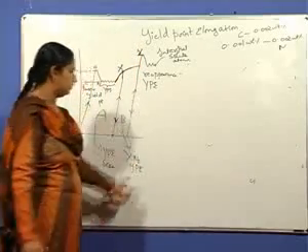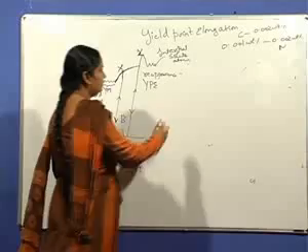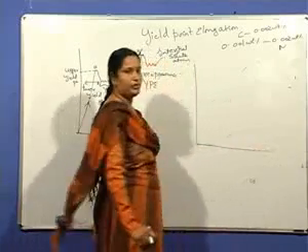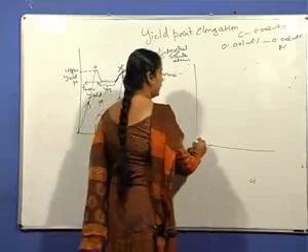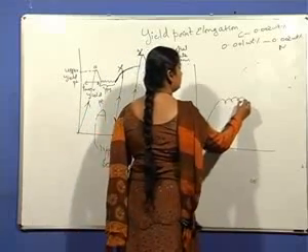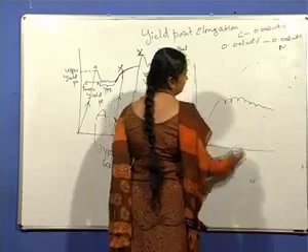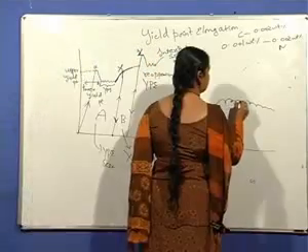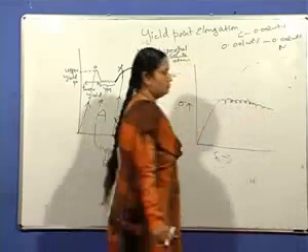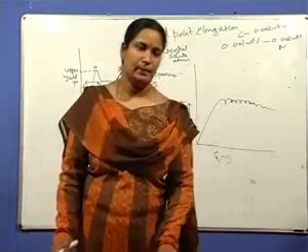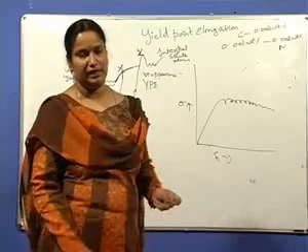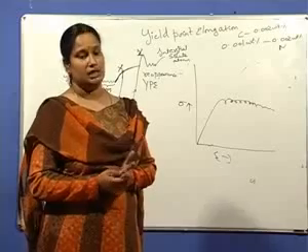So that is static strain aging, and dynamic strain aging is strain aging that occurs during plastic deformation, at slightly higher temperatures, around 200, 300 degrees.